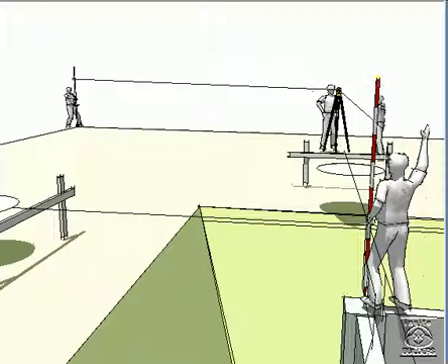The instrument is then pointed to the foundation or some other working point to transfer that elevation to the construction. The pole measurements above the pointed end may be higher or lower than the work point, but the markings on the pole give the relative differences between the two.